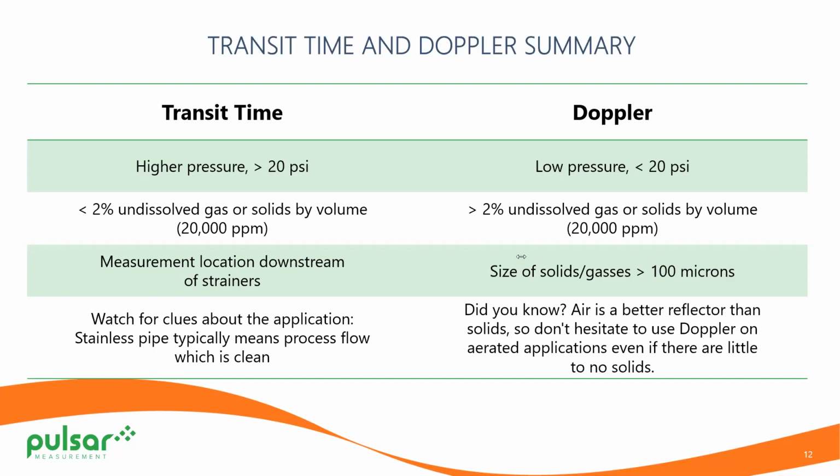And I think this might be answered further down. It's time of flight, so if spacing is wrong, accuracy will be off. That's true. And spacing can be wrong and still get a good signal strength. That came from AJ Weezy, who's one of our representatives who installed a lot of these meters. And I think he understands.